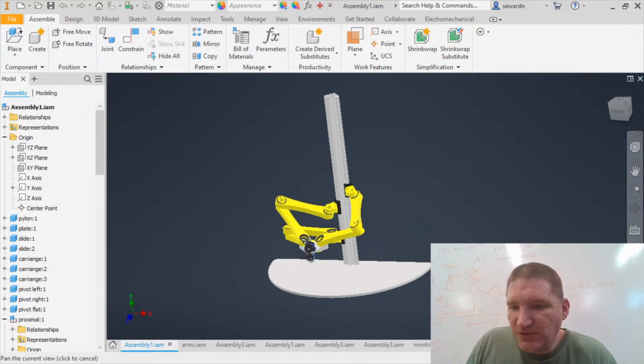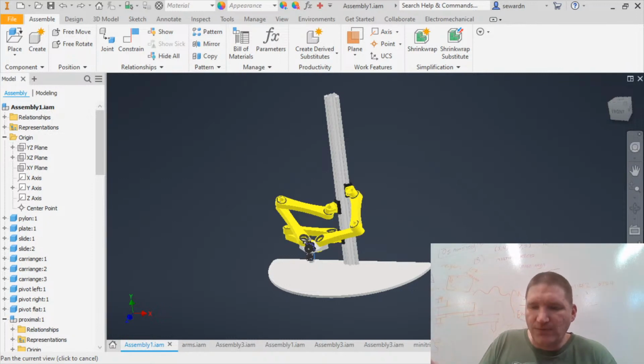Let's see. 2 linear rails either side of an extrusion, perhaps. Yeah, 2 rails would be better than 1 as far as if you straddle with carriages on each. But I think I'm going to use an MGN 15 rail, and those are rated for like 10 times more torque than I need.